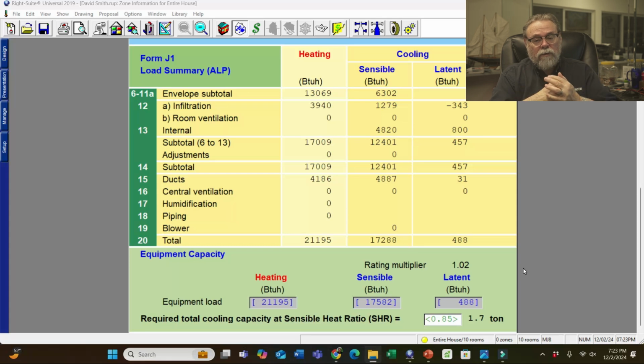So she's going to get a variable speed. And so we're going to do a 3 ton because it's going to be running at 30%. 30% of 3 tons is going to be very low. It's 9,000 BTUs basically. So she's going to be less than a ton at start out. If she needs it, it'll ramp up as it needs to because it's 30% of 36,000. So 0.3 times 36,000 equals 10,000 BTUs. So she'll get 10,000 BTUs out of the unit when it first starts, and then if it needs more cooling, it'll ramp up. So sizing it becomes less of an issue, but we do need to pay attention to this.